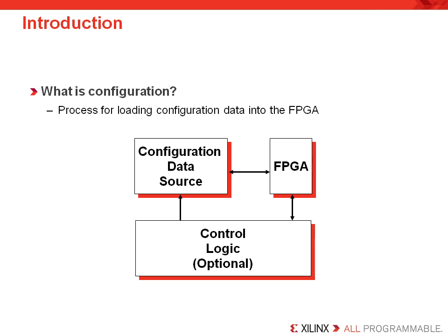If the designer did not want to build this extra control logic, there are additional master configuration modes that use dedicated control logic inside of the FPGA to program the FPGA with a bitstream stored on a variety of memory components. The supported memory devices include a Xilinx PROM, a Byte-Wide Peripheral Interface or BPI PROM, or a Serial Peripheral Interface or SPI PROM. Depending on the configuration mode you choose, there are two types of data paths, serial and